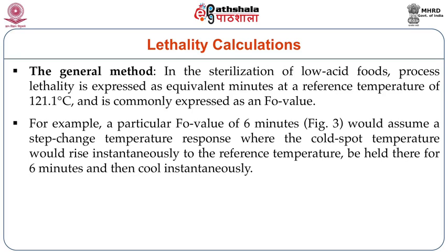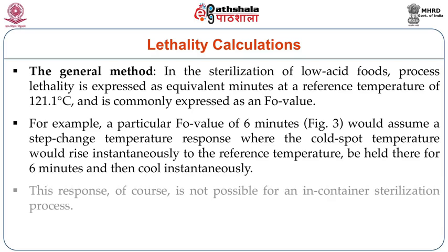For example, the F0 value of 6 minutes, as shown in the figure being projected in the slide, would assume a step change temperature response where the cold spot temperature would rise instantaneously to the reference temperature, be held there for 6 minutes and then cooled instantaneously. As shown in the figure, it is not possible for an in-container sterilization process.